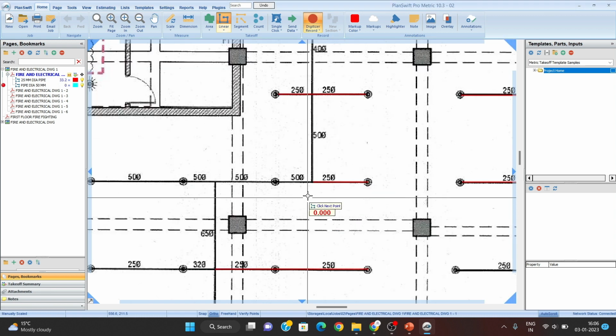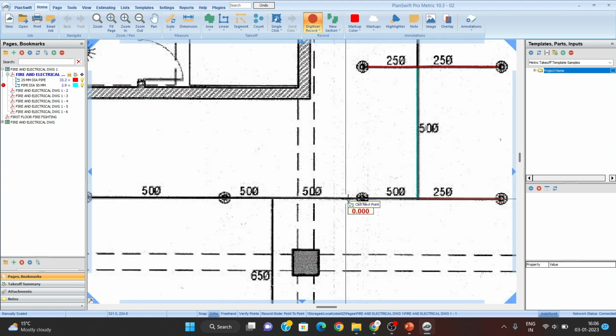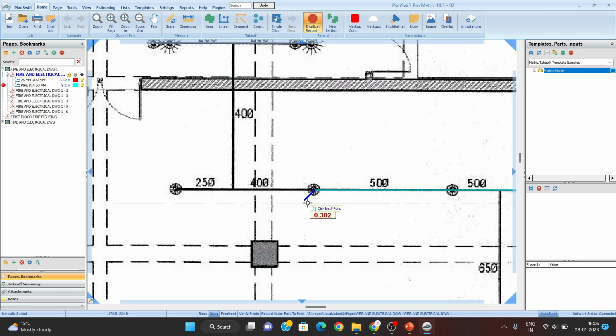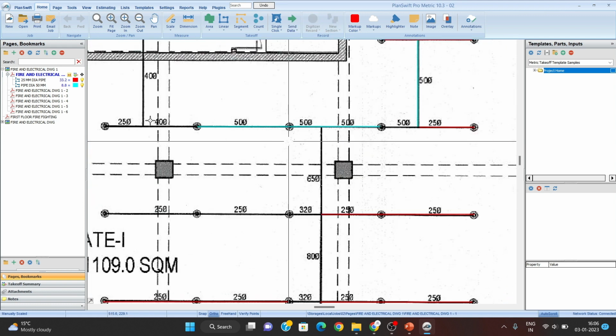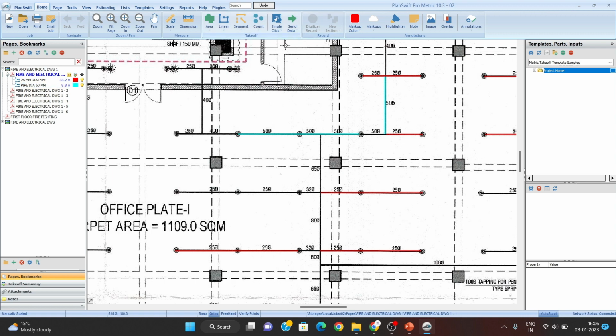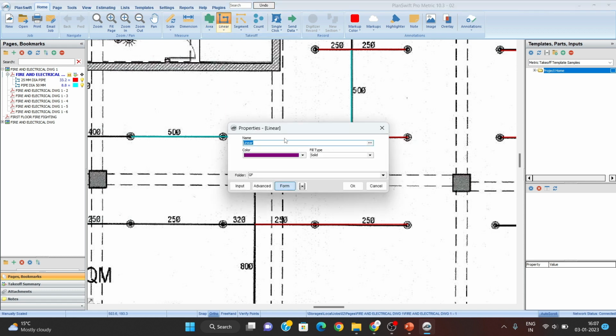Okay, then okay. Now just as previous, mouse left button, right button, new section. We can take all the 50 dia pipe through this. See, left button, then again here left button, right button, new section. See, for 50 dia pipe I have selected this, taken 8.8. If you want to again go for 65 dia pipe, then again fresh new linear, 65 dia pipe. You can use this purple color only, ground floor already selected.